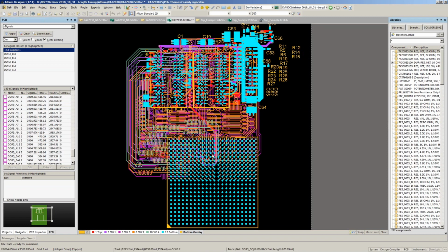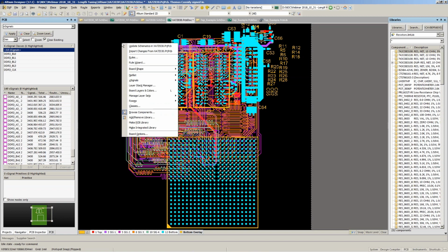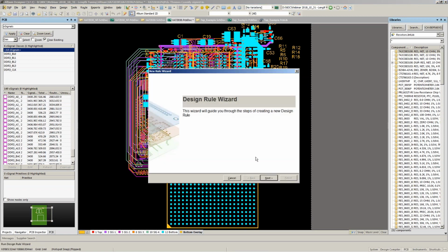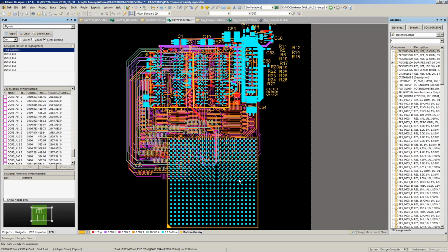As you saw Paul presented earlier, you can do this manually where you can select the first source chip, select your destination chip, and then basically create all of the signal groups you need. Altium gives you a little bit better. So I'm going to hit some shortcut keys, DXW.